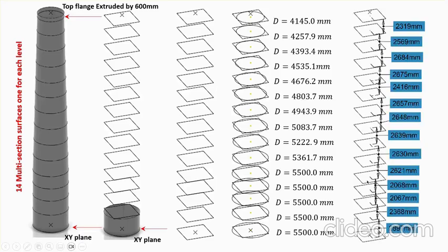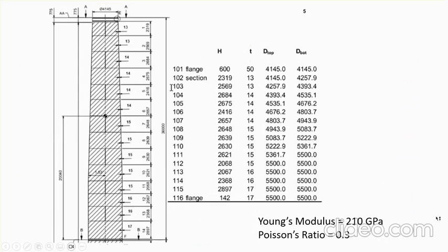Now, the heights of the planes are here. So basically, the height of each layer is given there. So I'm going to be using those. This is actually coming from the website. The material is assumed to be linear. Obviously, we're doing linear buckling, so all you need is the Young's modulus and Poisson ratio, and these are the values that are used in the paper.